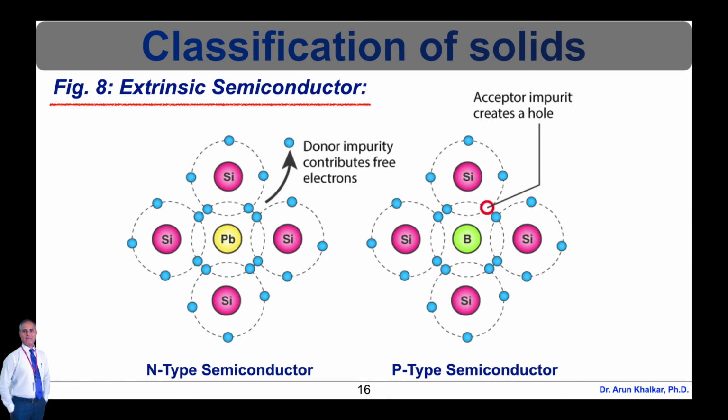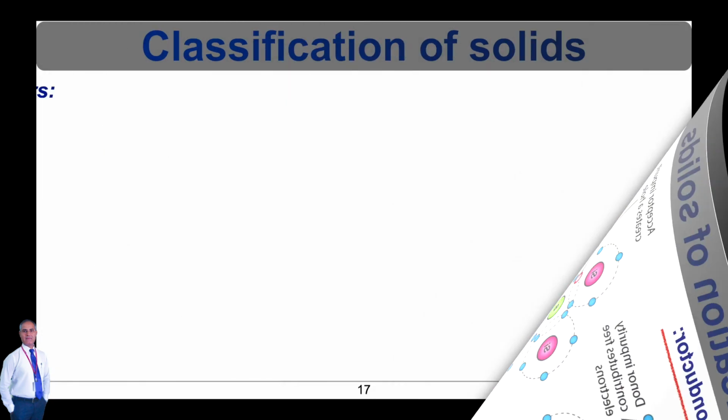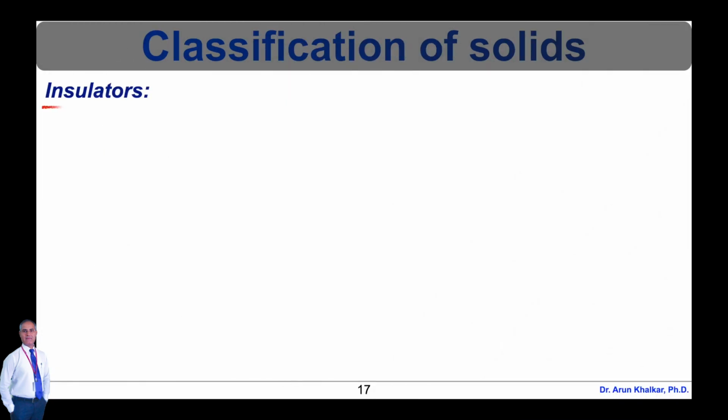With the increase in the number of impurities, holes, the positive charge carriers, are increased. Hence, it is called P-type semiconductor. The crystal as a whole is neutral, but the acceptor becomes an immobile negative ion. As conduction is due to a large number of holes, the holes in the P-type semiconductor are majority carriers and electrons are minority carriers.